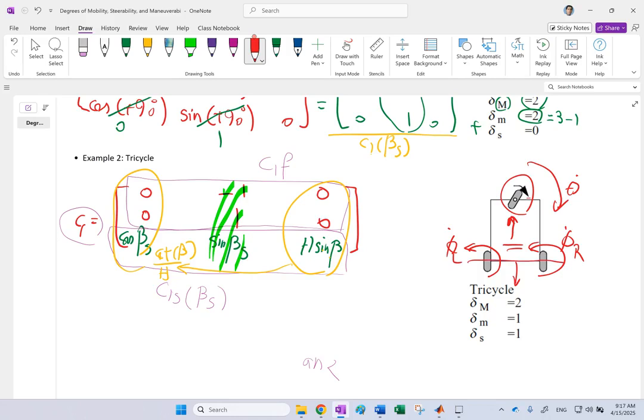If these are a differential drive, then you don't need steering. They will overlap. So the steering can get rid of that differential drive for you, and instead of using a differential in the back or two separate motors, you can simply have a single motor here and make your mechanism a lot simpler.